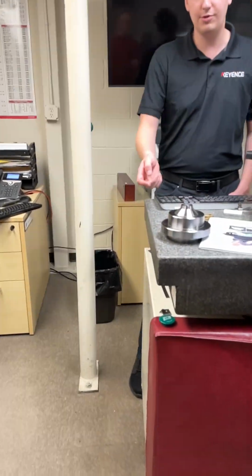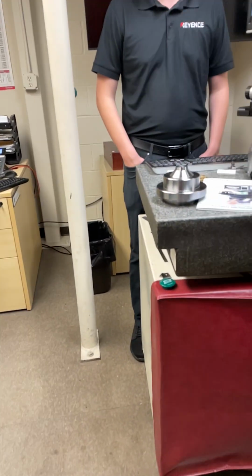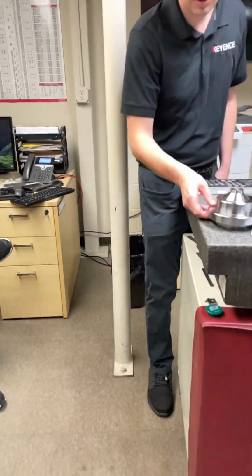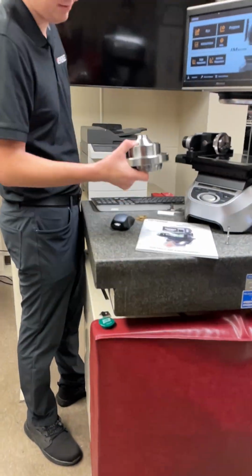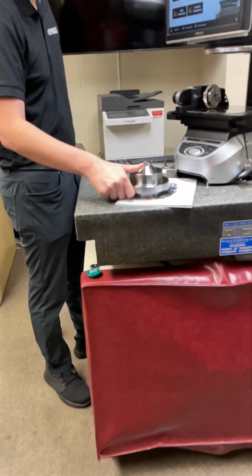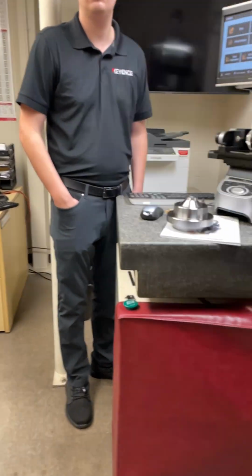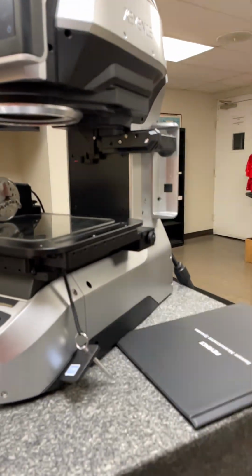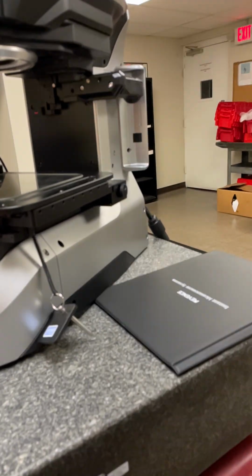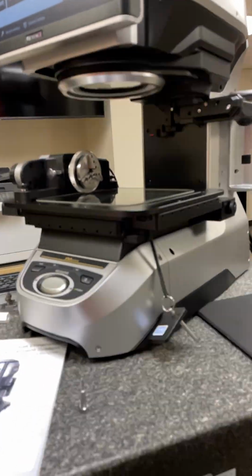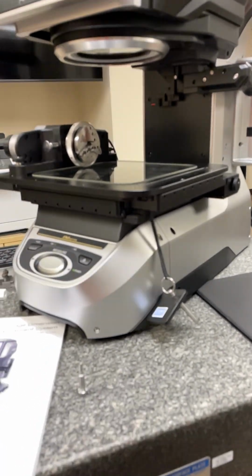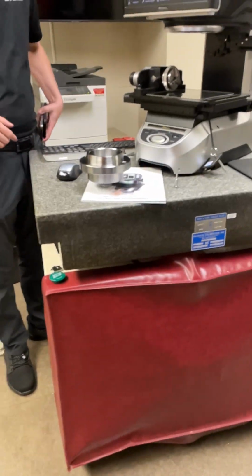So I can do everything but that inside bottom radius, pretty much, doing it like this. That's what we've got an issue with. And we can put the CAD model on the CMM and try it, Joe. Yeah, you can do that. Just pick up this diameter as your datum, and then the top face, and then CAD depth.